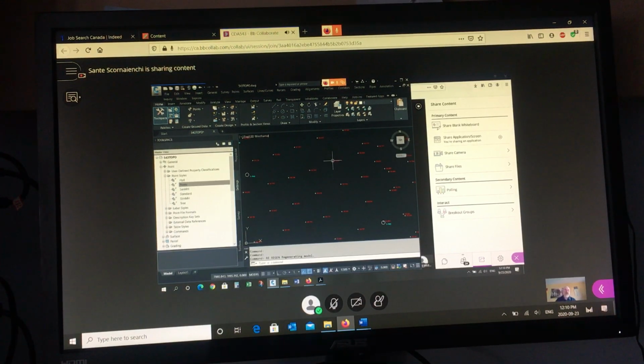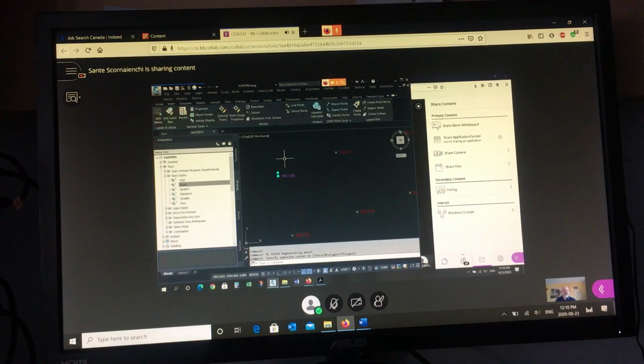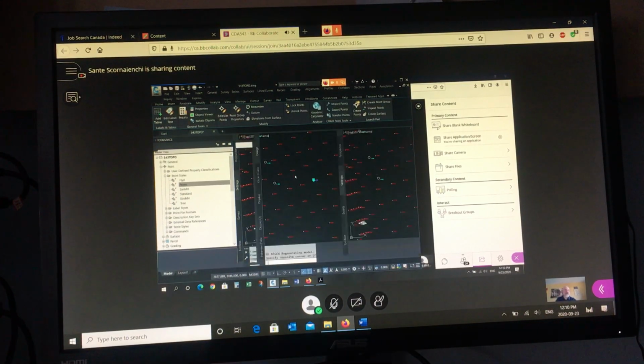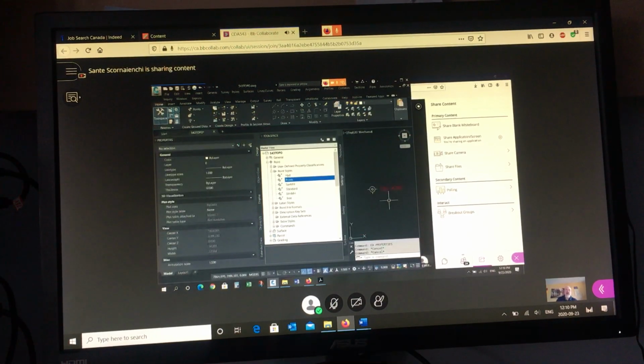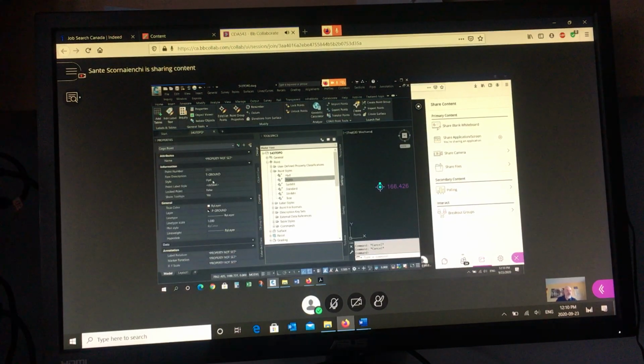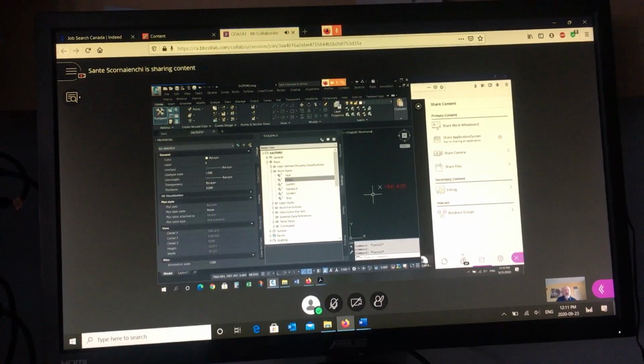The other way it gets screwed up is if I pick one and change it from default to something that's got no display. If I hard code this and it always looks like a hydrant, well, why does my tree look like a hydrant when it's supposed to be a tree? Because you hard coded the style. If you don't leave that as default, and a better word than default would be by group, then it won't react based on the group membership. It'll react based on hard coding.